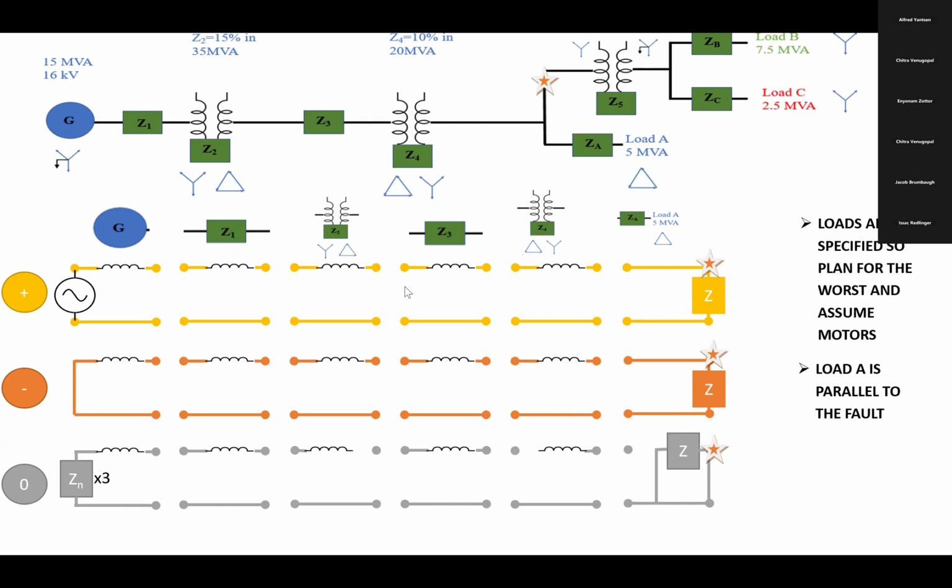Whereas in the zero sequence, the Y side is having an impedance, a common ground, whereas on the delta side, there is no common ground. So that should be left open. And then again for the impedance here. So this impedance, this is the line. Just represent it by the impedance. And then again the transformer. So this side is delta, so this side also should be delta. You cannot connect a delta with a star. So delta must be delta.